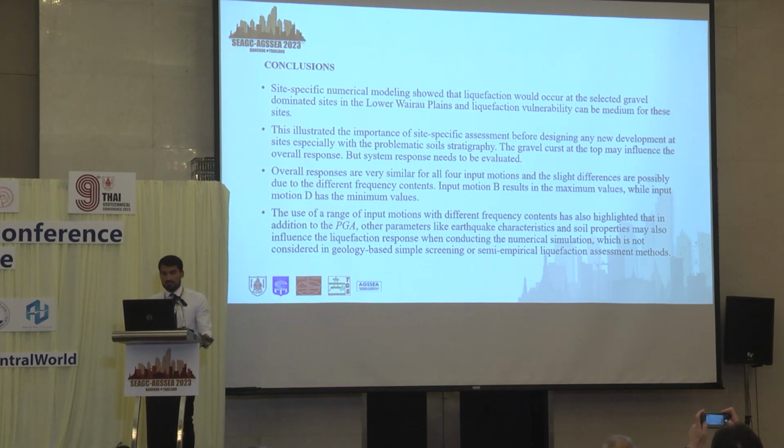So these are some of the conclusions from this paper. Site-specific numerical modeling showed that liquefaction would occur in sites A and B, and this can also lead to a medium vulnerability of liquefaction. It also shows the importance of site-specific assessment in addition to CPT-based or just the geological or geomorphological-based analysis, because we can see the pore water pressure generation and stress-strain behavior. Overall response is similar for sites A and B, and the use of a range of input motions with different frequency content highlighted that in addition to PGA, other parameters like earthquake characteristics and soil properties may also influence the liquefaction response when conducting the numerical simulations.